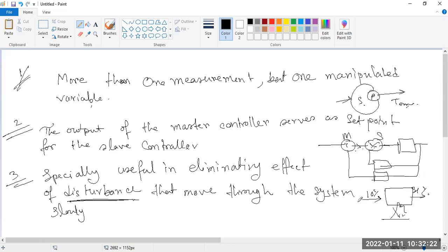There's only one loop required. But here this is called disturbance because first time this is 10%, then this is 20%, again this is 10%. It may vary. So this is called the disturbance, which we have to deal with. In feed forward control, we also apply some control strategy as per our experience, as per our rule base. But here, we don't know how much feed is coming. Sometimes it is 10%, sometimes 20%, sometimes 30%. So it is varying. So this is called disturbance.